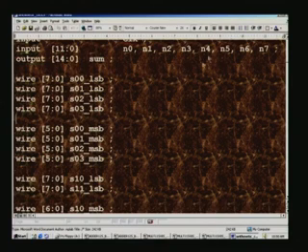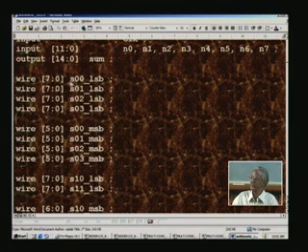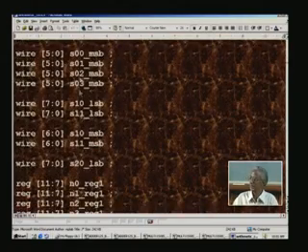During the course of the other statements in which we work out the arithmetic portion, we will be encountering very many intermediate signals. Some of them may be with assign statements, and therefore they are all declared as wire, and the width of each is also declared here. For example, we will be adding the LSB as we had mentioned in the pipeline partition earlier, and we will also be adding the MSB with the carry of the LSB addition and so on, and they all have to be declared here.